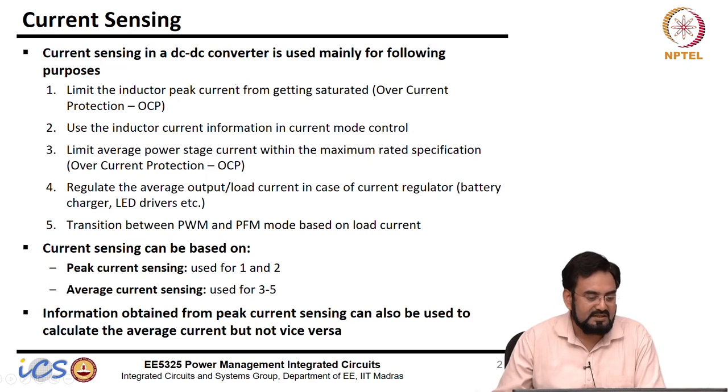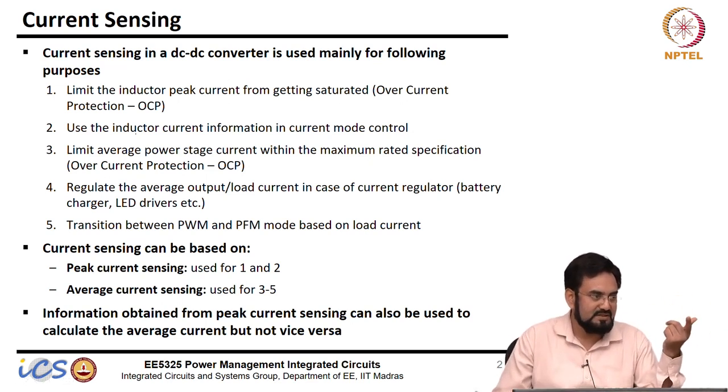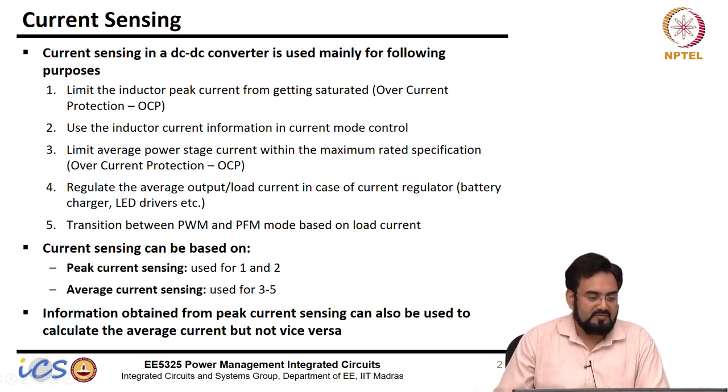But in the case of a switching regulator, we have an inductor also. So we have to protect the inductor as well from getting saturated. We need to limit the inductor peak current to keep it from saturating, and we call it overcurrent protection, OCP.